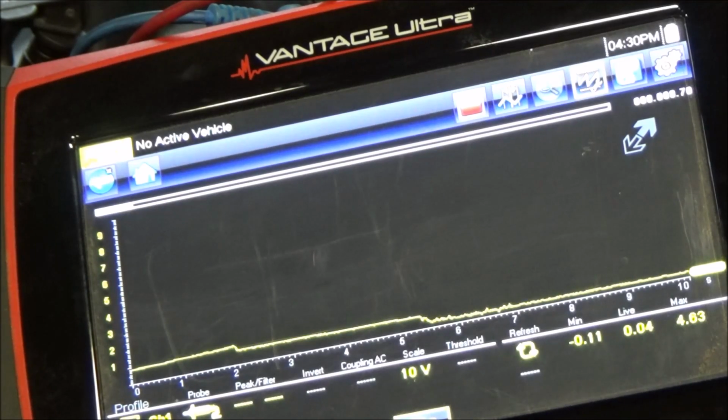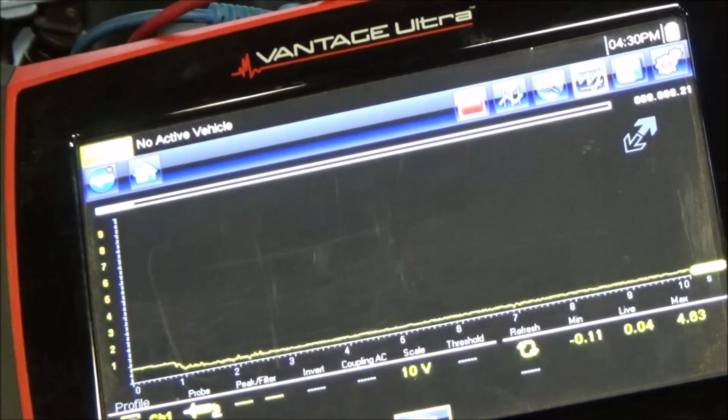We can see a little bit of fluctuation in that line there, guys. It kind of implies an open circuit. So really this would be a bad portion of this potentiometer. There's a little lever inside of it that sweeps along a variable resistance